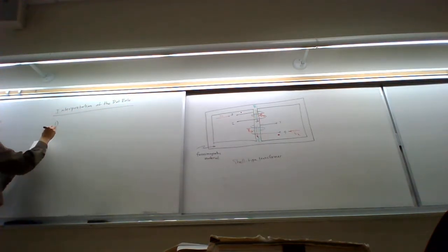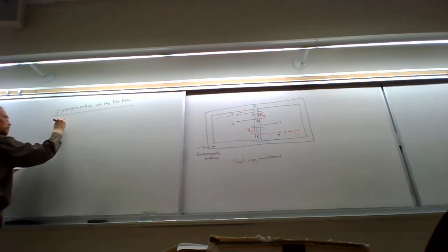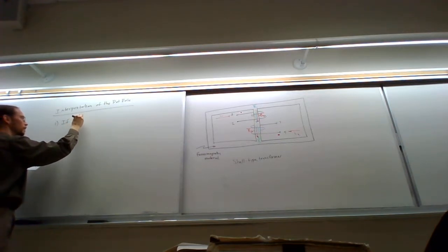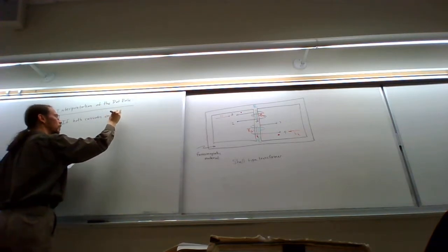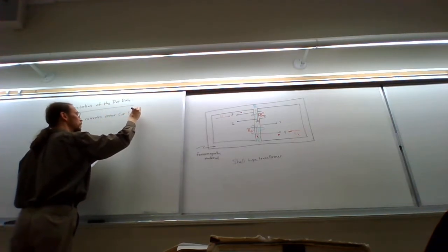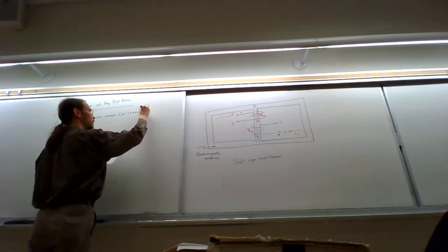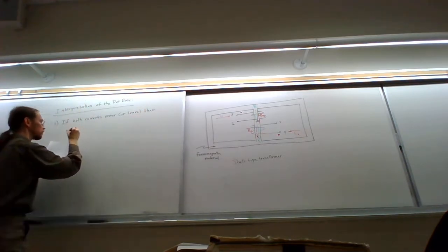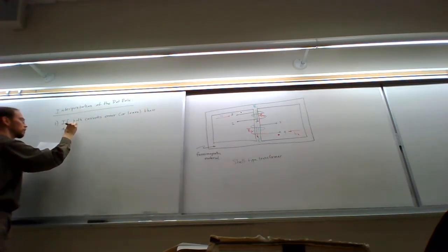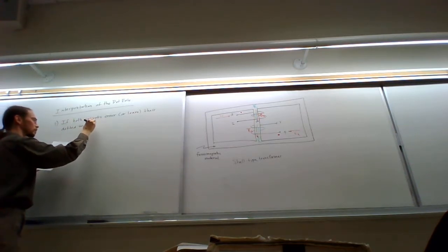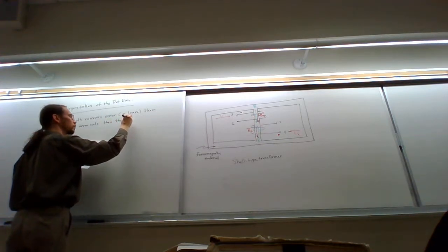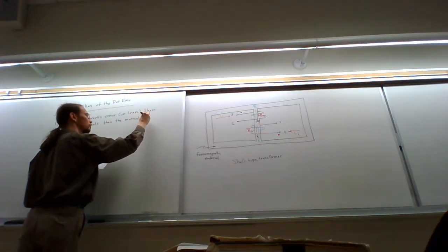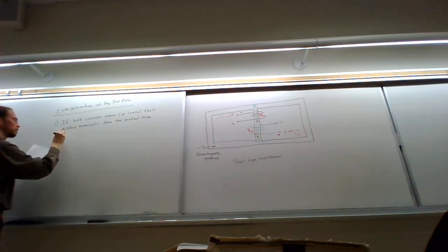And it is that if both currents enter or leave their dotted terminals, then the mutual term is positive.